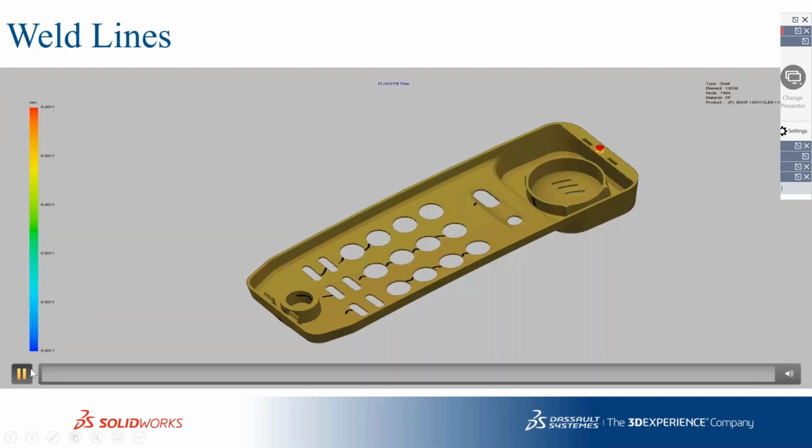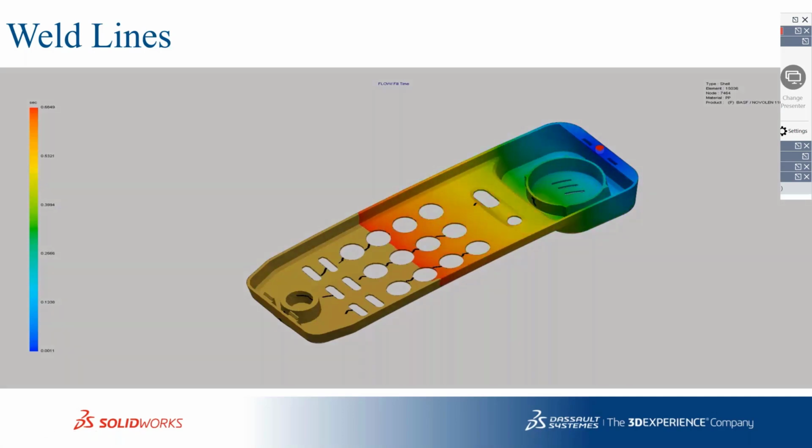Weld lines, as we were discussing, are where there are flow fronts meeting. The flow is unidirectional from the gate location, and it flows across in the core and cavity, and there is a possibility that your flow fronts meet at one point, where it diverges from the insert here and meets here. So you will get the weld lines there. To overcome it, you can change the gate location accordingly, so that you can maximally avoid the flow fronts meeting, and you can also design the gate such that the flow fronts meet at the edges of the part, so that weld lines are not visible.